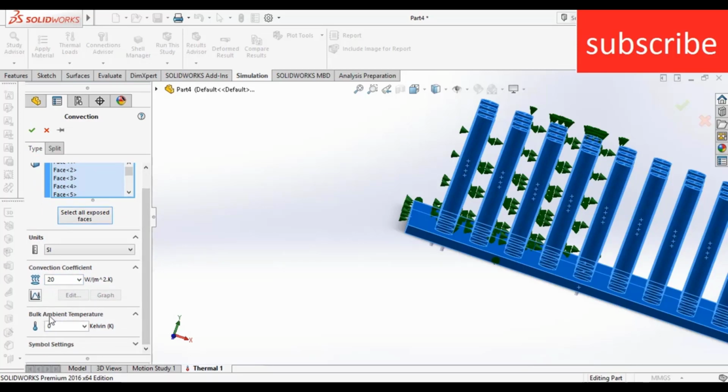Here it's asking for the bulk ambient temperature. Bulk ambient temperature is the temperature of the surrounding. For example, you are boiling your water, so the temperature of the boiling water is 100 degrees Celsius, but what is the temperature of your surrounding? For example, it is 25 degrees Celsius, so you will enter the value of 25 degrees Celsius here, that is the bulk ambient temperature. So here 273.15 plus 25. Remember, here the units are in Kelvin, so the exact value is 298.15 Kelvin. Now click OK.